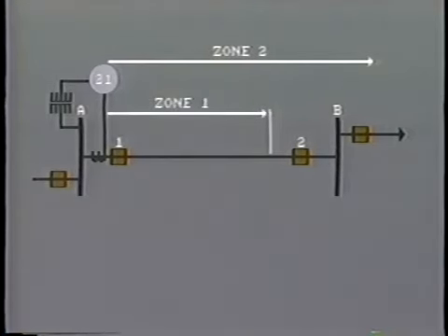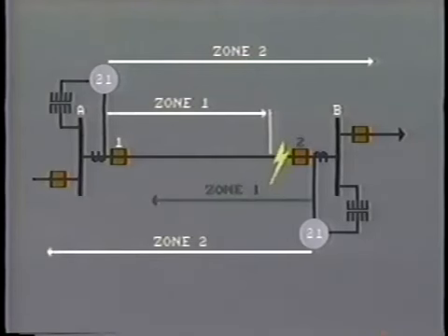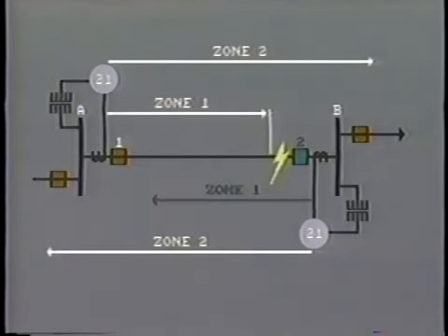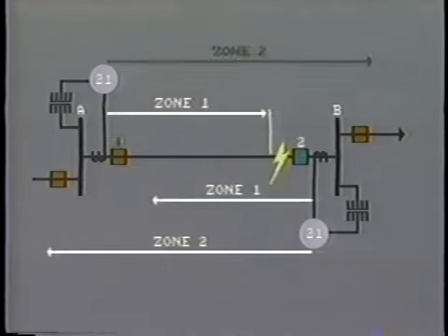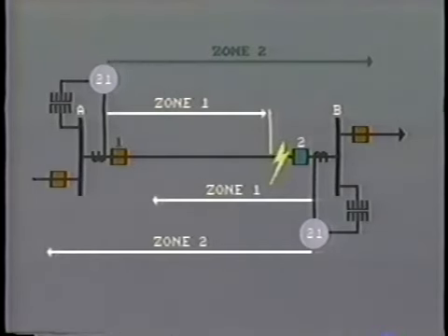If a fault occurs within the remaining 20% of the line, then the breaker will trip on the second zone, but this will be time delayed. Even with distance relays at both ends of the line, the problem persists. In this instance, breaker 2 trips at high speed on the zone 1 element of the number 2 distance relay, but the clearing of breaker number 1 still has to wait until the zone 2 element at this bus has timed out.